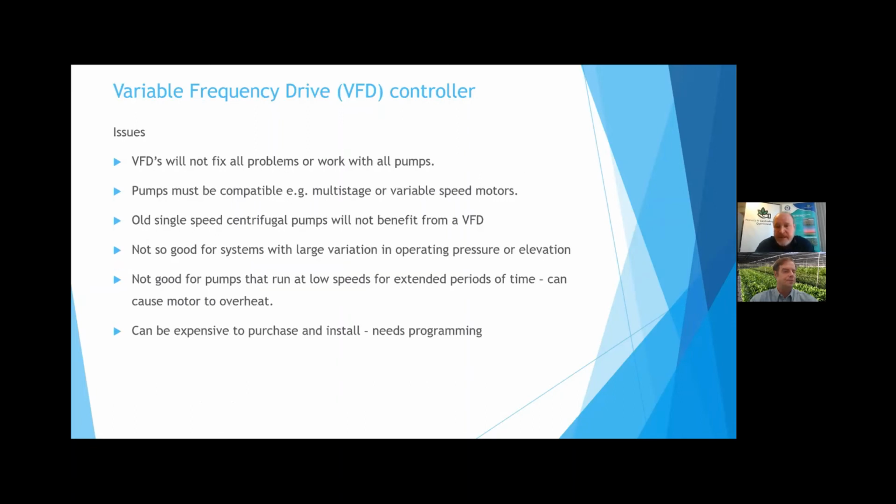There are some issues that you have to be aware of, like the pump must be compatible for a start. If there's a large variation in operating pressures or land elevation, they can cause erratic pump operation, or if the pump is oversized and it needs to operate at low speeds for an extended period of time, that can lead to the pump motor overheating.